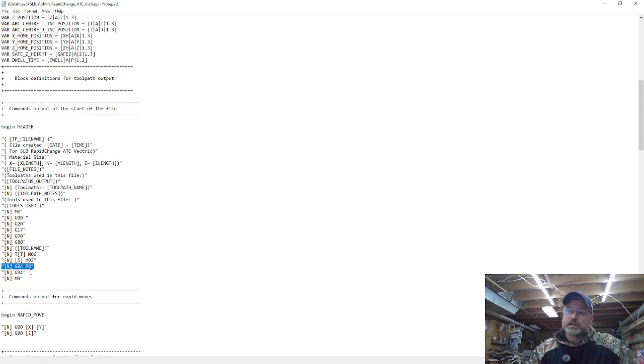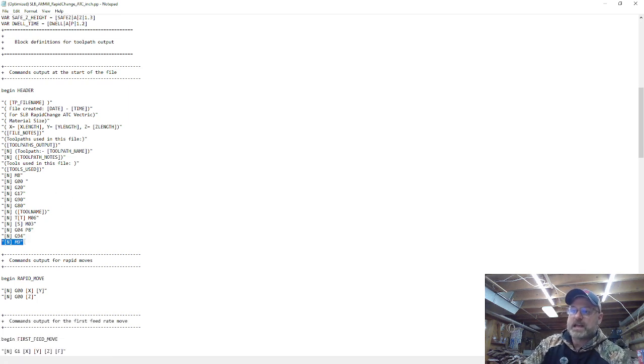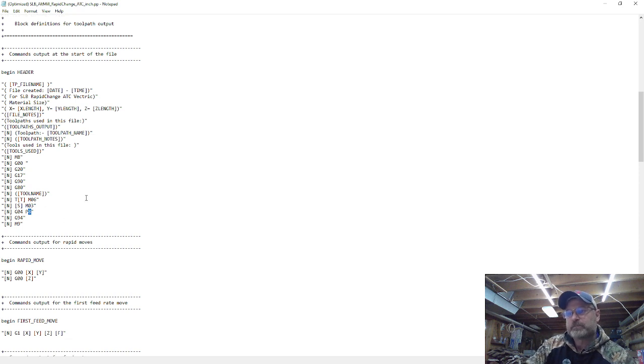Once it's ramped up and paused for 8 seconds, then it's going to start moving to your first program feed moves, and then it's going to close your dust boot. So that's what that's going to do. So you can adjust those, add your M9 codes, add your M8 codes if they're not already in there, and then adjust your pauses for how long you want your spindle to ramp up.